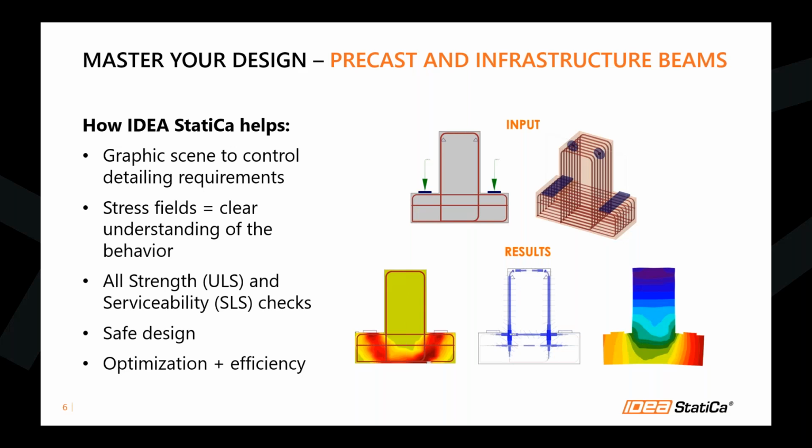The detail application gives you control over the detailing of reinforcement. You see the behavior in the graphic scene. So you immediately see how the structure will behave, what is the expected behavior, and you get all the results for not just ultimate limit state checks, but also for all serviceable limit state checks. So even if I use strut and tie method for the same type of structure, I would see all passing checks.